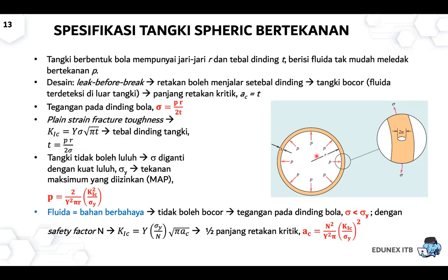However, for hazardous fluids, hazardous materials, we can't apply leak before break. So we can ensure, for example, the stress in the wall, this one here, and then for example we introduce a safety factor, and then we can calculate the thickness.